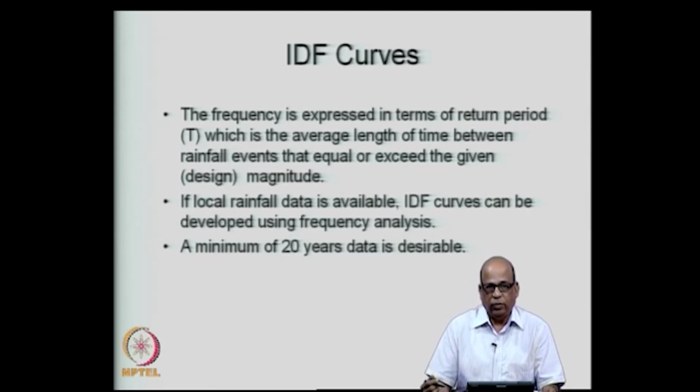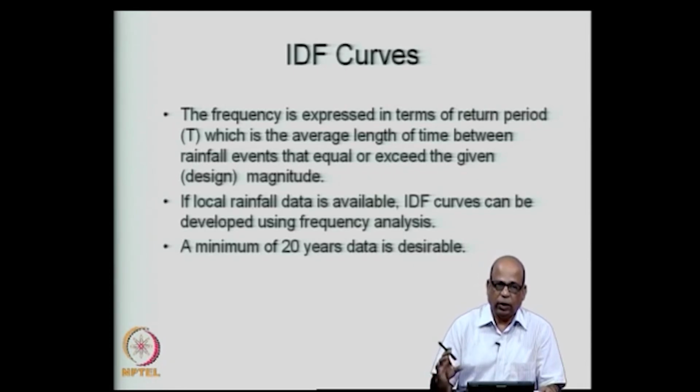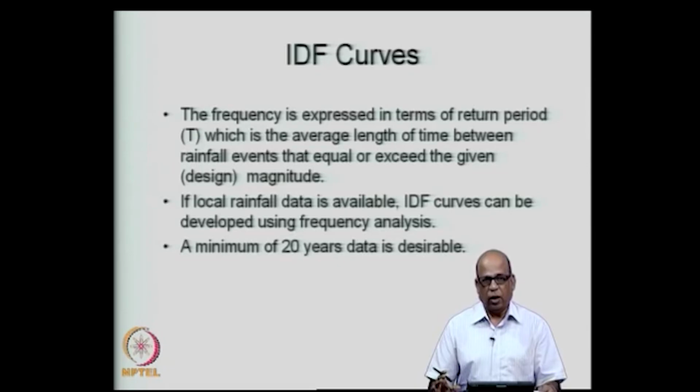Then we have the frequency. Frequency, as I mentioned, is expressed in terms of the return period, and the return period is fixed for a particular design, or various return periods can be examined for a particular hydrologic design based on the engineering judgment, and also based on the importance or the criticality of the design itself.